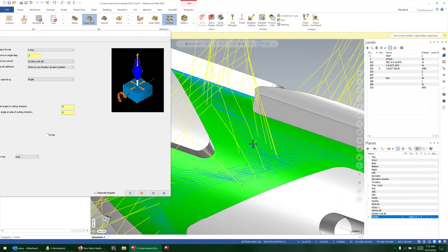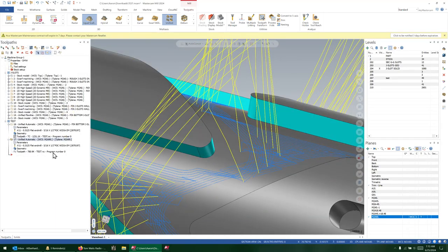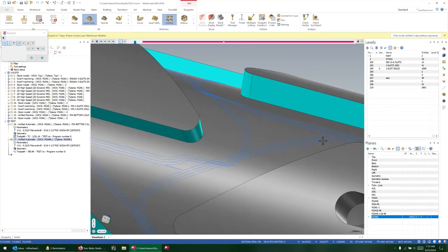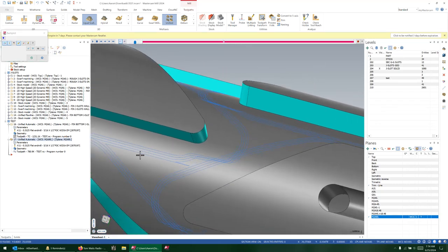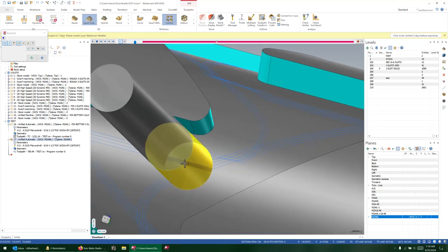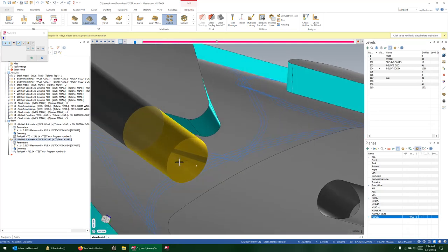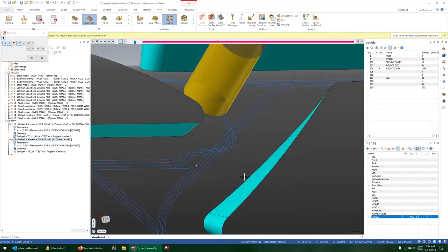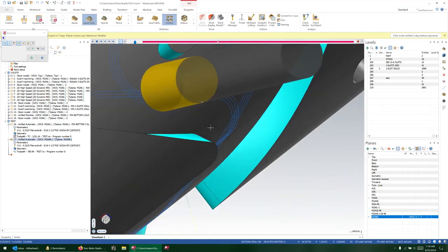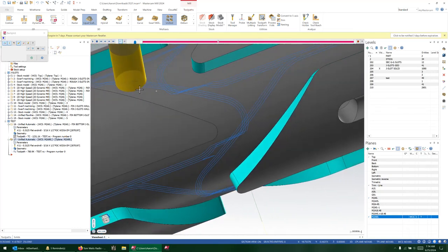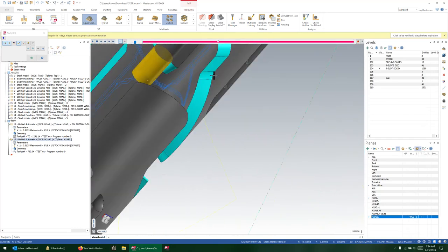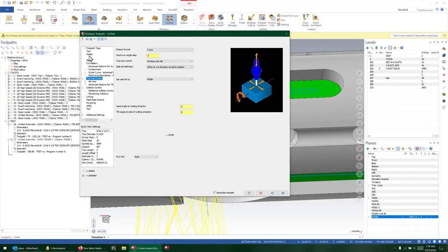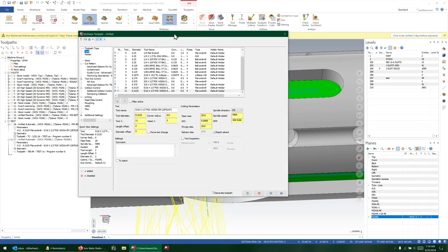All right, well, that made it look a whole lot uglier. Now, what's happening there? So as we come around, let's just follow one of these patterns that gets ugly. So I'm just going to choose this one. So you see that the tool's kind of moving around a bit. Well, because we locked it into 4-axis mode, it's actually bouncing back and forth, trying to keep different parts of the tool in contact for that individual vector. Now, if you change this to a ball nose end mill, you're not going to see that because it's not bouncing around on the flat of the tool, right?